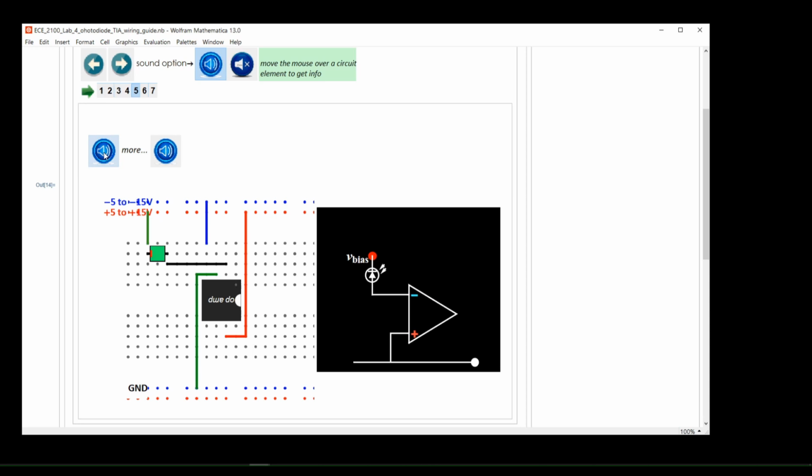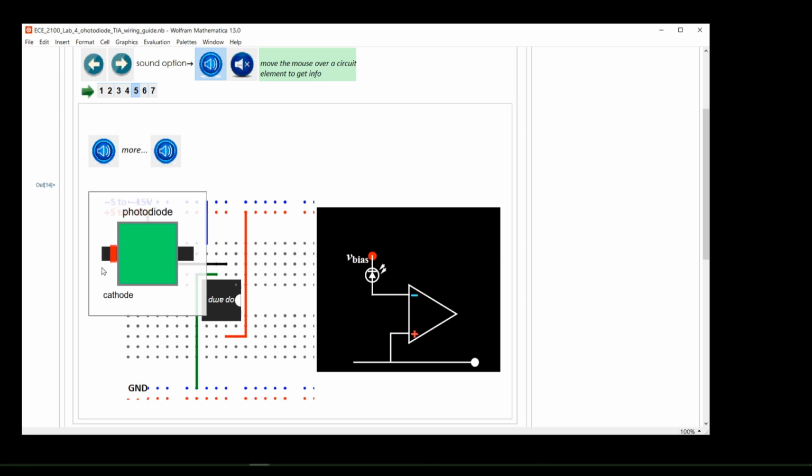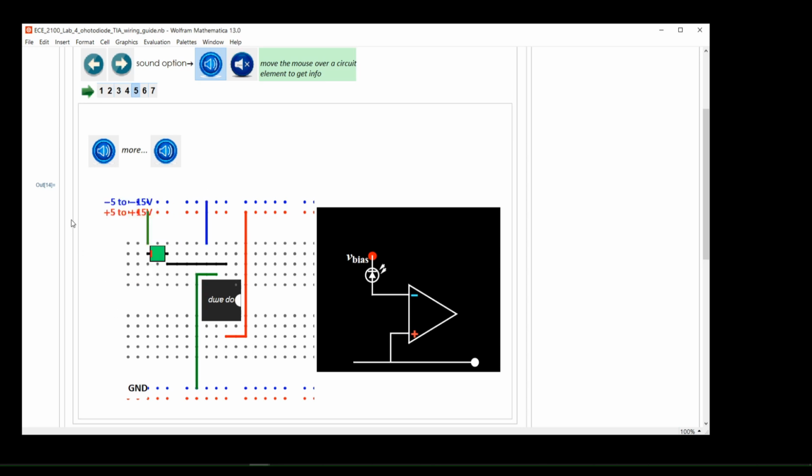If the photodiode is bare and not in a protective housing, hold the photodiode with a tweezer, or a fine tip plier, and insert it onto the breadboard. Be sure the cathode, not the anode, is placed toward the positive voltage supply rail for a wire connection, while the anode is oriented toward pin 2, the inverting terminal of the op-amp, and connected with a wire.